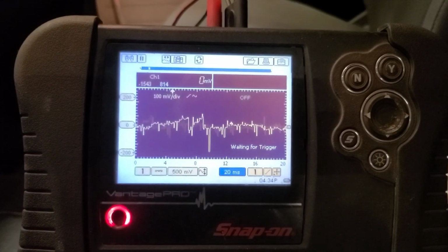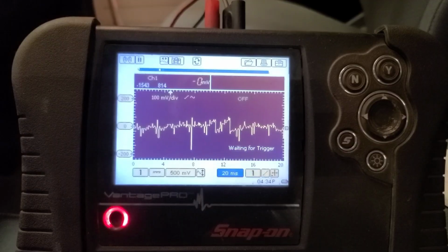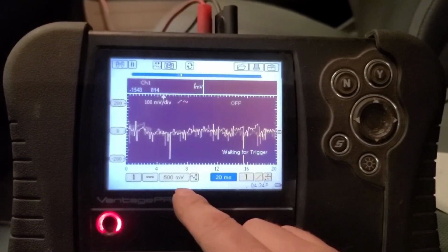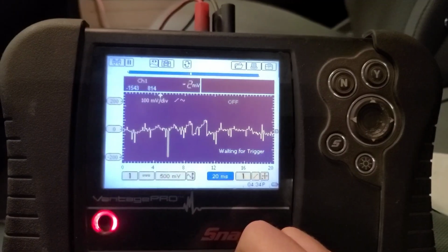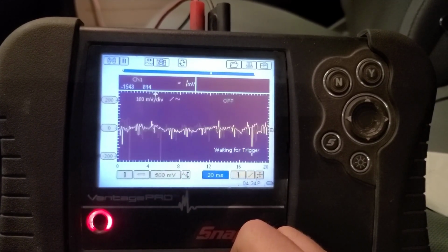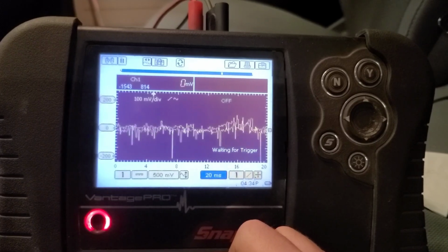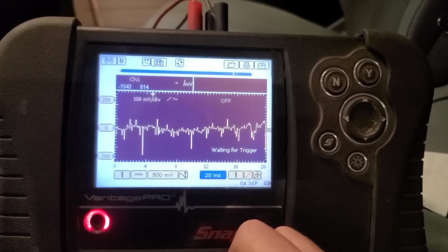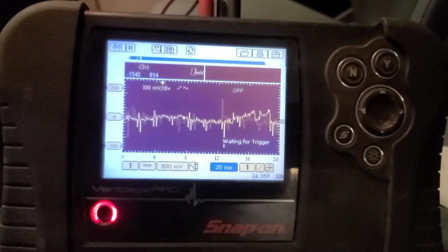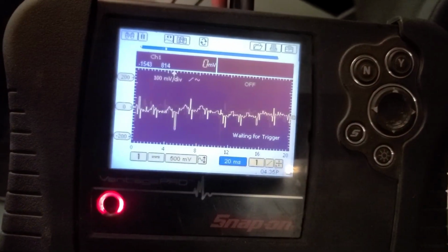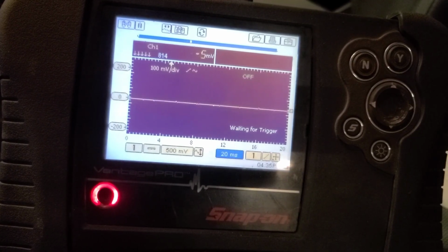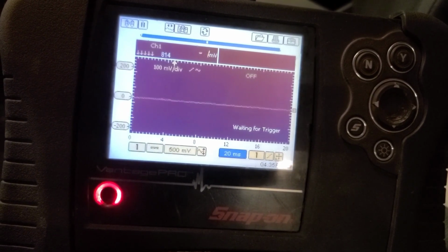So would you look at this? This is the output shaft speed signal voltage, AC coupled at 500 millivolts. Now I'm running it obviously, so I'm thinking, is there electrical interference caused by the ignition or the alternator? The alternator diode ripple looks normal. But watch what happens when I turn it off. Okay, it goes to 0, flat line. Turn the key back on.